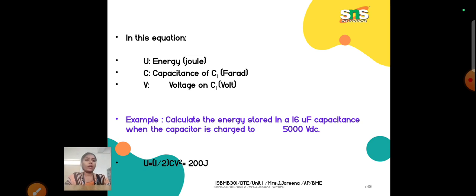Inside the defibrillator, we have the main component, that is a capacitor. That capacitor will be storing the energy based on its capacitance value, and then it will be releasing the energy whenever it is required. The energy delivered to the patient will vary from patient to patient or application to application, so we have to design based on the demand or application. Therefore we should know the capacitance of the capacitor, so that we get to know what energy will be stored in the capacitor.